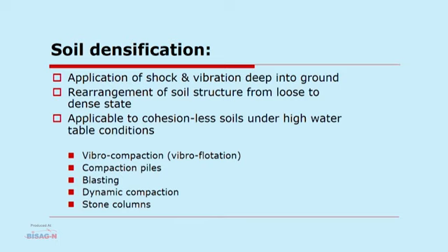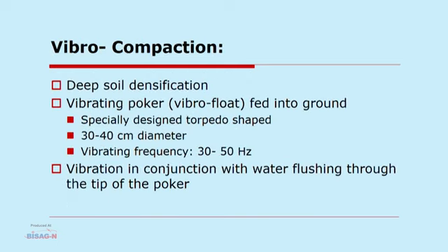By using vibro compaction, compaction piles, blasting, dynamic compaction, or stone columns, we achieve soil densification, which is required to be taken for increasing the SBC of the soil. First, the vibro compaction. Deep soil densification happens.